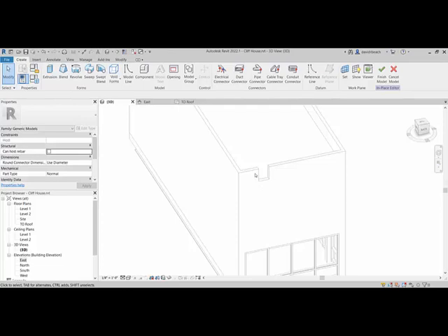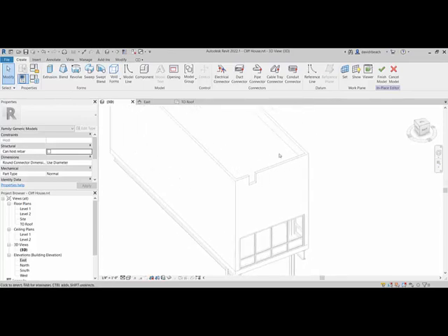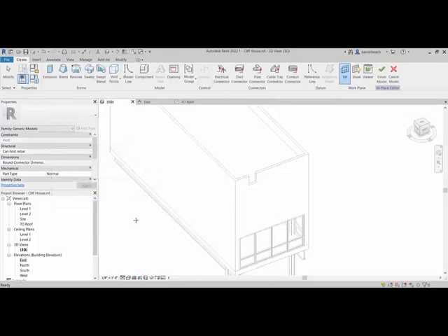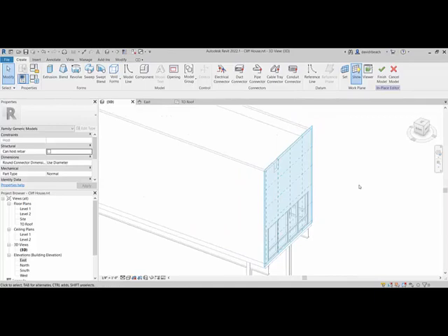We know that that is existing on this wall, so I don't really need to worry about reference planes. Okay, so reference planes are super important. I'd love to show you guys how they work, but 9 times out of 10, you're going to have a reference plane existing to work off of. So in this case, we want to work off of this wall as our reference plane. So I'm going to go Set, pick a plane, and select that outside edge. And you don't need to turn on show, but I like to do it so that you can all see what I'm referencing.